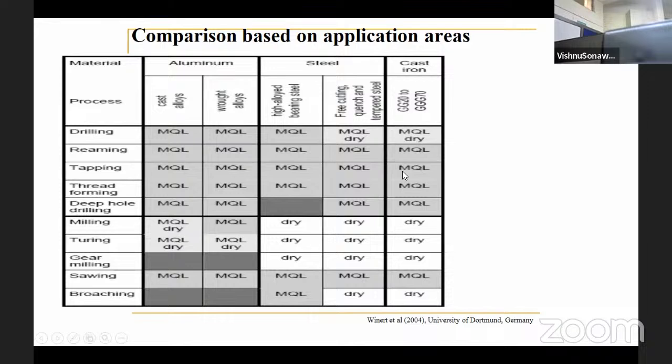We are using the minimum quantity lubrication. But for steel, only free cutting steel, dry machining will be used, and for cast iron.